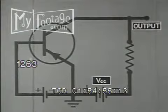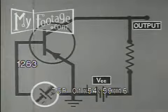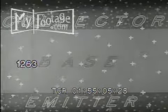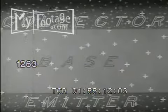Thus, the switch is a little slow to respond. There is also a brief delay when the switch is turned on due to the transit time, the length of time it takes the carriers to travel through the base. The collector current cannot reach its full saturation value until holes are arriving in adequate numbers.